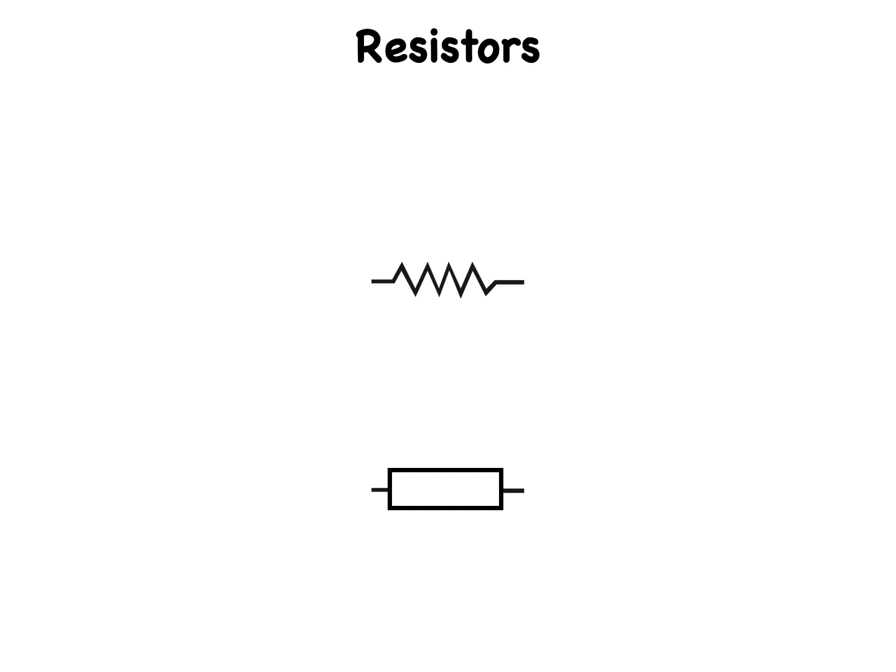A variable resistor has the ability to change ohmic value by means of a slide or rotary tap that can be moved along the resistive element. The variable resistor is usually set to one value, and it remains at this point until manually changed. The electronic circuit, therefore, sees the component as a fixed resistor. However, when a variable resistor is required for the proper functioning of a specific circuit, it is necessary to indicate to any person who might build it from a schematic drawing that the resistor is actually a variable type.